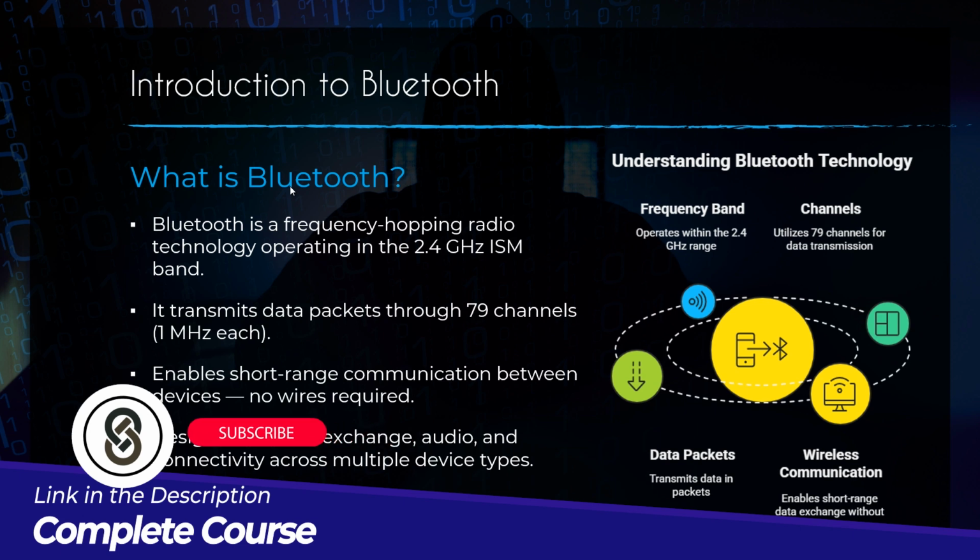Bluetooth is a short range wireless communication standard that uses radio waves in the 2.4 gigahertz band. Similarly to Wi-Fi, which also uses the 2.4 gigahertz band to transfer information between devices, it relies on a frequency hopping spread spectrum method, which means it rapidly switches among 79 channels.